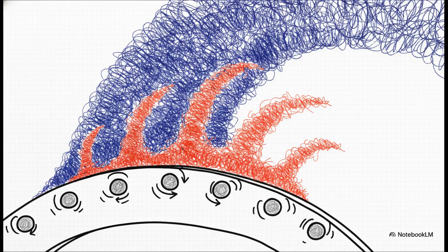So, the crucial point is how the machine physically fights back. As that sudden flux tries to penetrate the rotor poles, it encounters the damper bars embedded in the pole faces. Through the process of transformer induction, this flux induces massive currents inside these copper bars. They essentially act just like a squirrel cage induction motor during a sudden speed change. These induced currents set up an opposing flux to repel the stator flux and maintain constant flux linkages. Honestly, these damper bars are your machine's heroic first line of physical defense. Now, let's see how this all builds into real-world engineering.